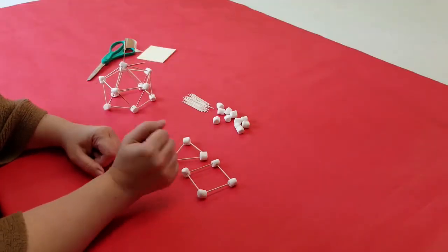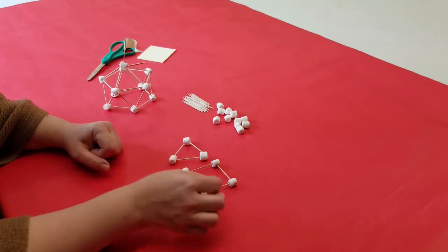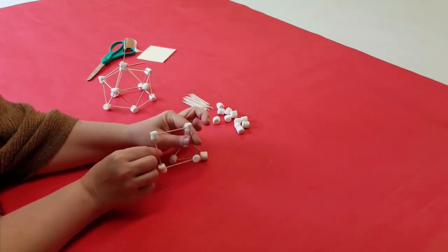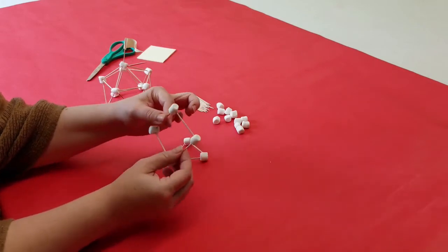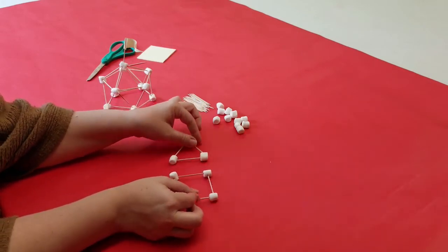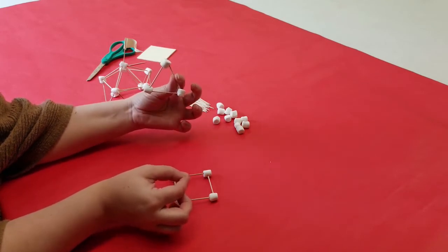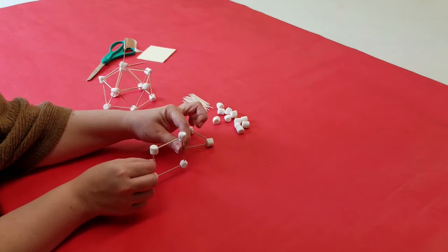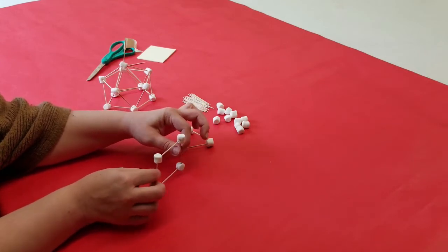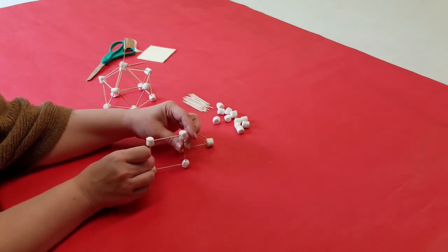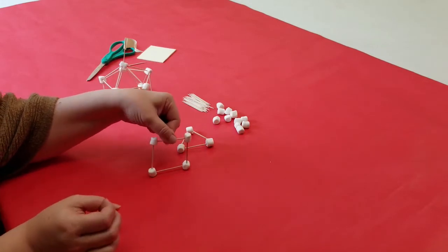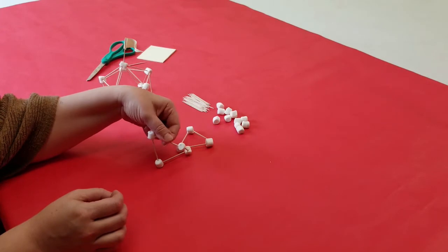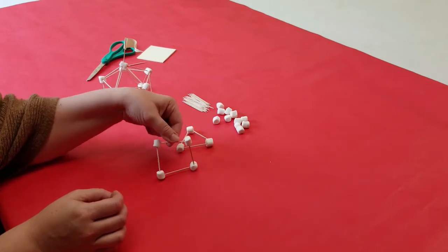Okay, so we're ready to start making our geodesic dome. To begin with, I've made a couple of structures here. A square, which is what everyone usually wants to start with in building a structure, and a triangle. And I want to show you the difference here in the strength and stability of them. Look at my square. If I'm holding it like this and I try to push down on it, look how it just bends and twists. It can swing from side to side. It's just not very stable.